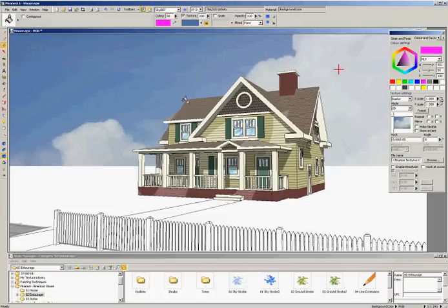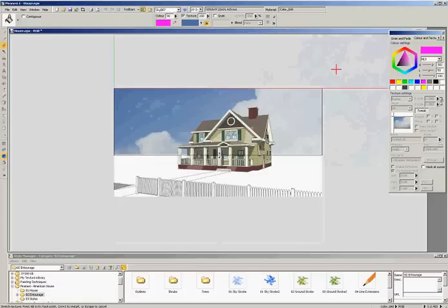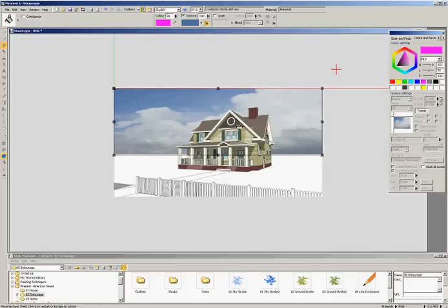I might tweak that if I decide it's too large an image. I'm just going to go into tweak mode, which works on any of the textures that I put in place. I could alter the angle of my brickwork or tiling or anything like that using tweak very easily. So I could scale my image accordingly. Come out of tweak mode, and I've got my background in place.